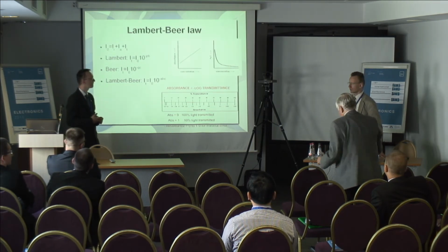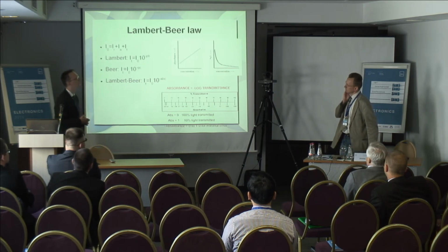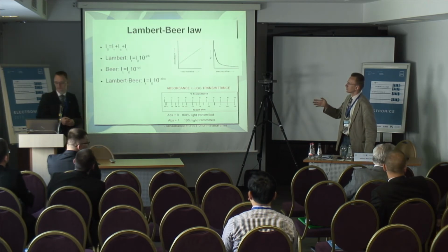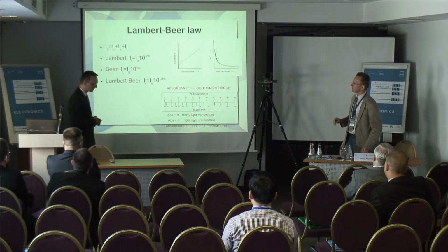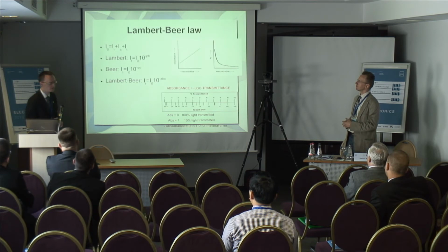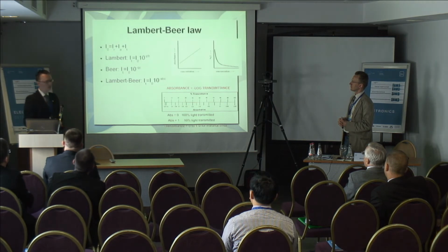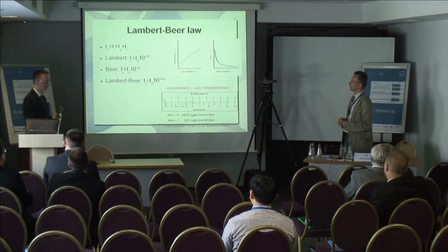Okay, thank you. A small question from my side. What are the disturbing factors in your measurement? Let's say, does it depend on the temperature of the liquids? The main problem in such measurements is calibration and the reliability of the calibration samples. Even experienced companies say, for example, that creating a dilution of up to or less than 5 NTU is almost impossible in most laboratories. So the calibration procedure is the most problematic thing here.